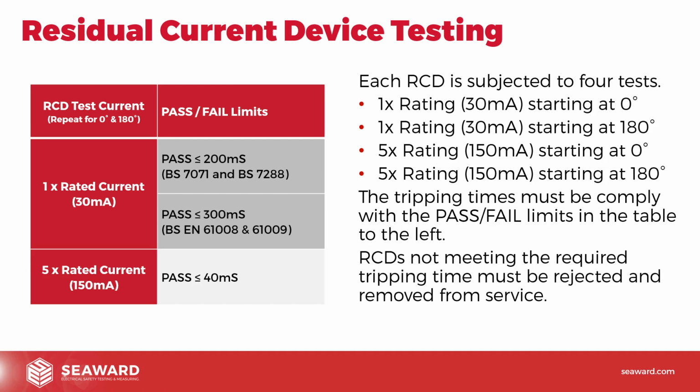It's not included in the IET Code of Practice, and it's not really a normal test that we'd carry out as part of PAT testing. Sometimes you'll see that carried out on the fixed installation and things like that. But it isn't a standard one. So if you're wondering where's the half times test gone, generally it isn't a test. It's testing that it doesn't trip. So I could test a switch or a circuit breaker the same way and it still wouldn't trip. So from that side of things, it isn't proving the performance of the device, so that's why it's not included in here. So hopefully that's given you a bit better an idea of RCD testing and the pass-fail limits.